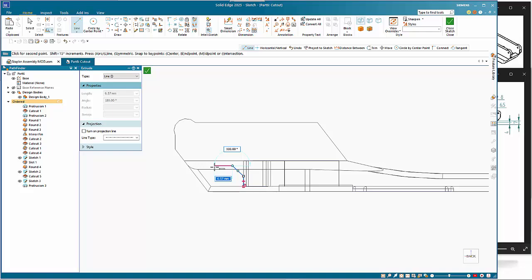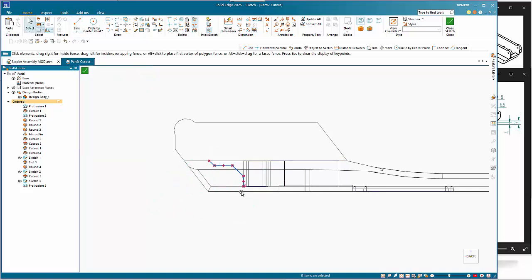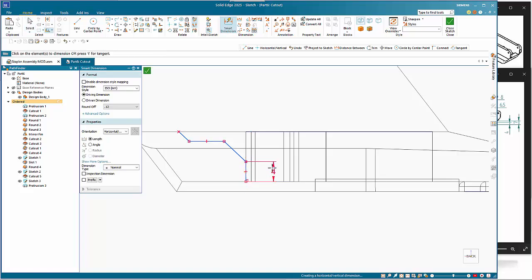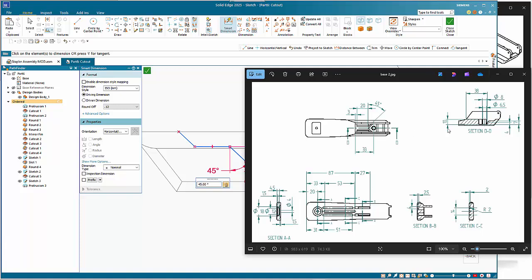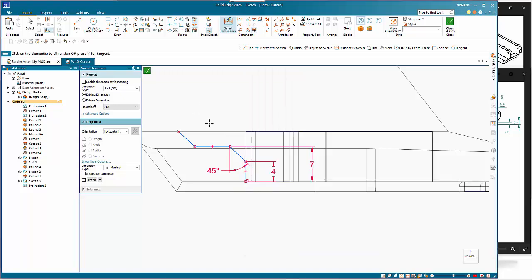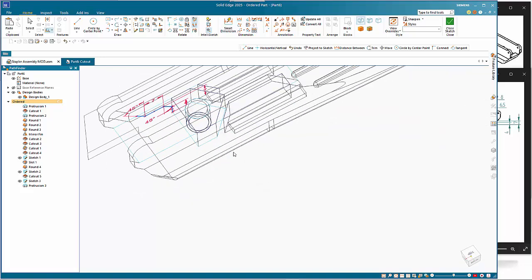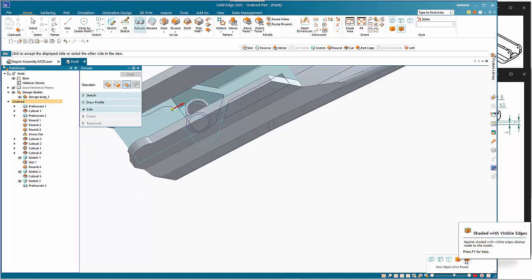I've just gone past where it should be, and again another 135 up to that top edge. So add dimensions. That one wants to be 4. That one wants to be 7. Create the angle on there, and again I'm not sure I've got a distance on that, so I will leave it as that, and then we can go angle, and I will make that 7 mil long and close that off. Let's change back to our hidden edge.